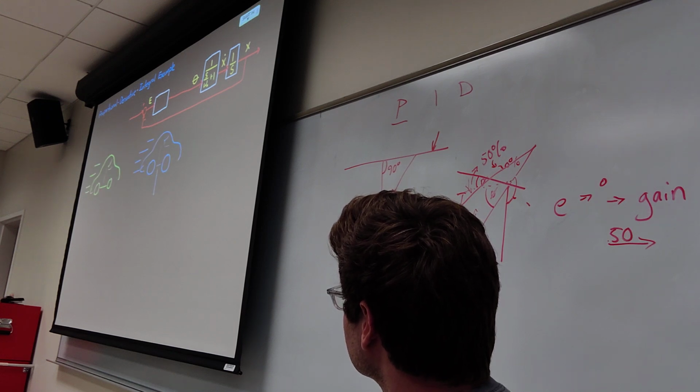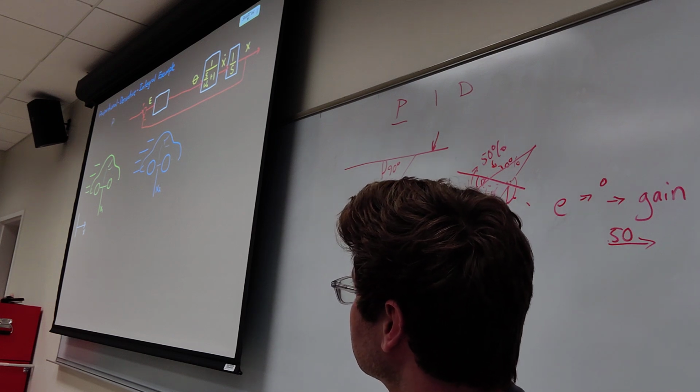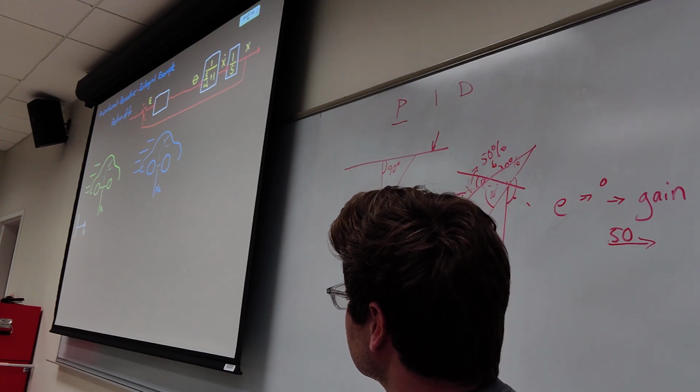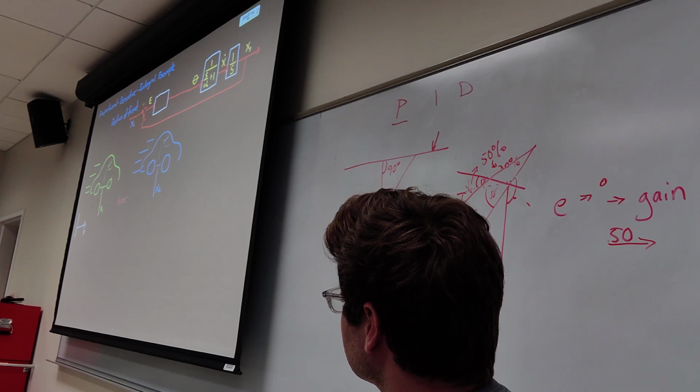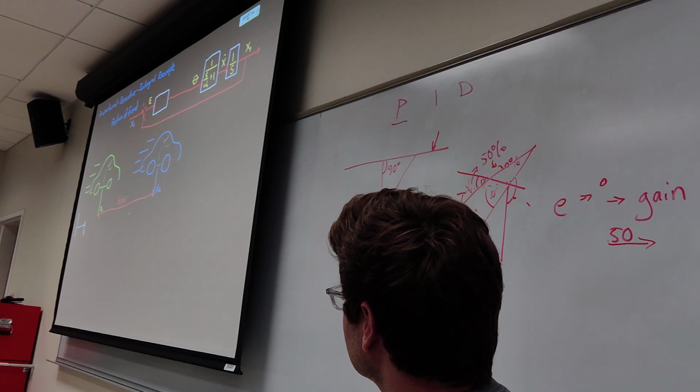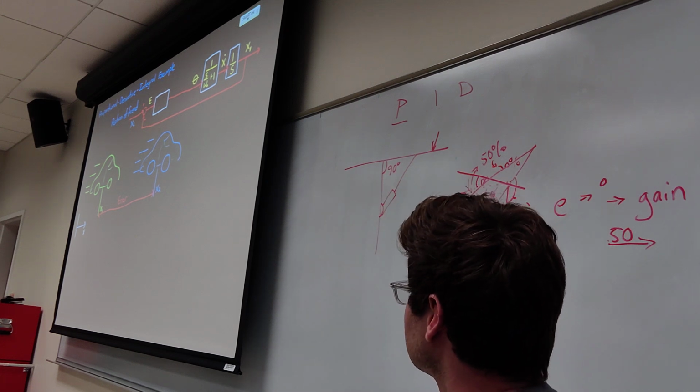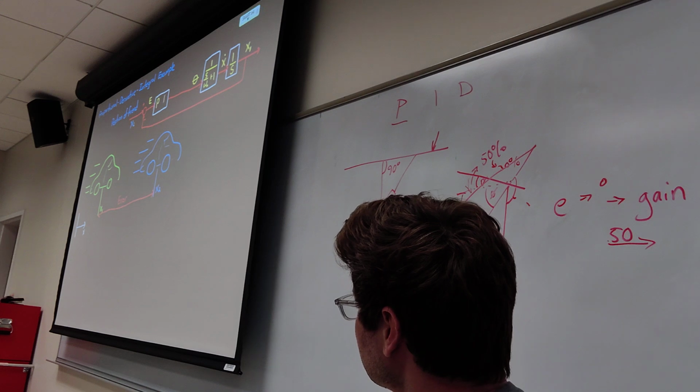And then I'll show you how PID control can help in that situation. Let's say you're in your car and you're trying to drive right beside your friend who's moving at a constant speed. In this case, the reference signal is the position of your friend. If the output of the controller is a pedal angle, it's easy to see that there's going to be a steady state error, and you will always trail behind your friend and never beside him.